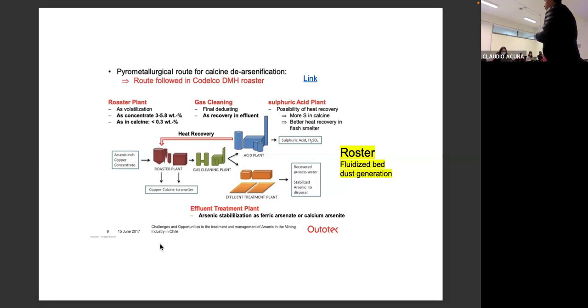So in the case of Chilean concentrate, specifically Chuquicamata, it contains a lot of arsenic, and I'm pretty sure different countries have the same. So the alternative was roasting. Whatever technology goes to roasting, a pyrometallurgical process that generates gases, is going to be really, really complex. It's difficult to control gases and dust in general, even with electrostatic precipitation. You will have particles going around.